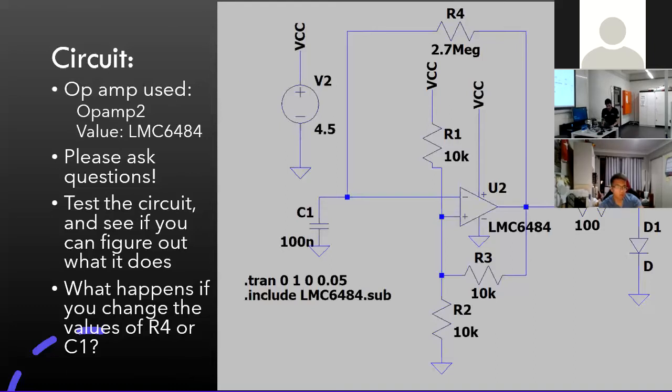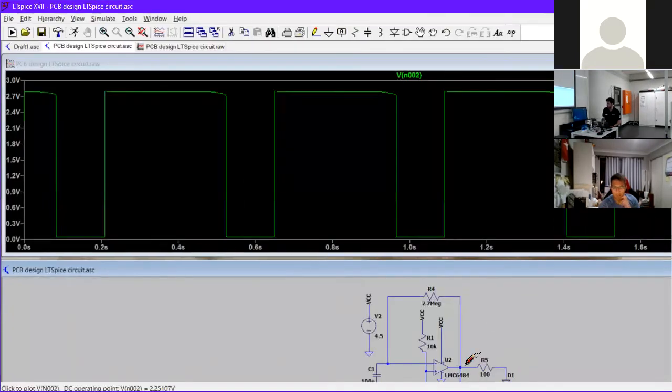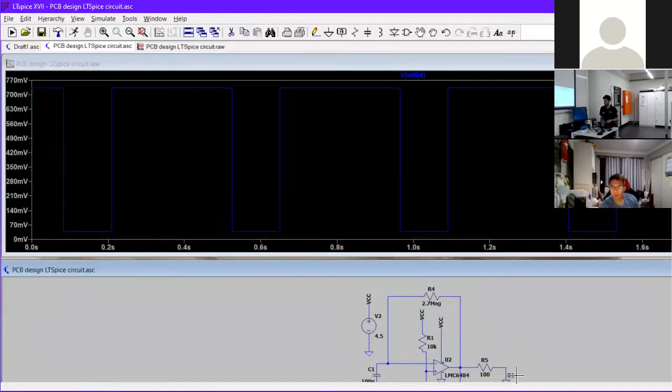So one thing we will do, have a look at the circuit. Is this going to appear over here? No, let's drag this over. There we go. Just looking at the circuit, if you have a look at it over here, we'll see actually a nice kind of vibration happening here. That's why it's 7 volts, because I'm scanning over here. Look at it after the resistor. You see quite a lot of drop.